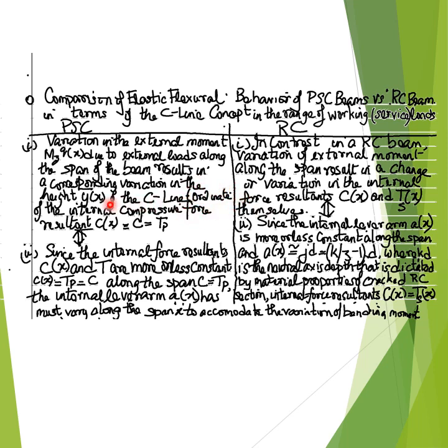that is also the ordinate or the height of the internal compressive force resultant C of the internal compressive forces in the concrete, which by the requirement of statical force equilibrium for any section should equal the internal tensile force in the pre-stressing steel, that is T subscript P, at all locations or coordinates X of the pre-stressed concrete beam.